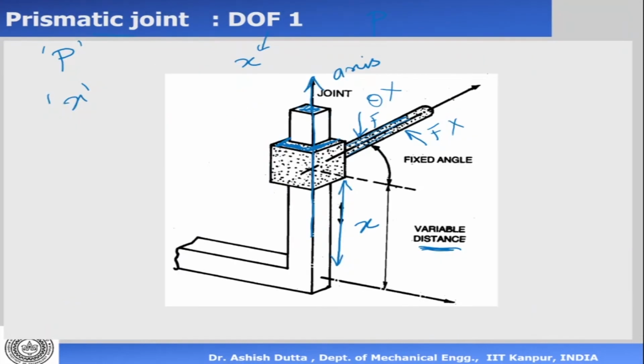Now, a straight degree of freedom may be required for assembly. So in the case of assembly, we require a linear actuator which is moving in a linear direction. But biological systems do not use this kind of joint. You'll never find a biological entity which uses a prismatic joint. We all use revolute, cylindrical, or universal joints.